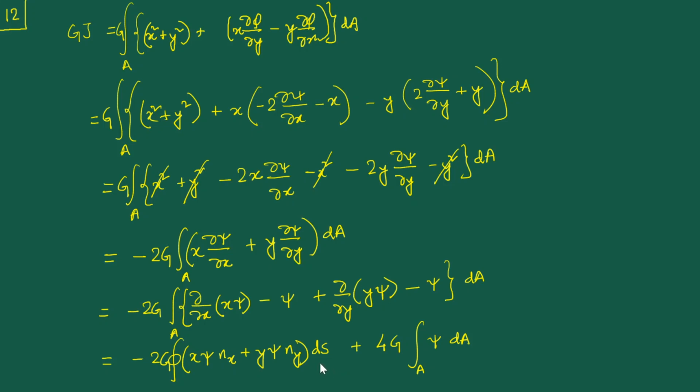All right, so basically what we have managed to do is to obtain the equations corresponding to the ones that we had obtained earlier involving the warping function, but this time involving the Prandtl stress function. And please note that unlike the approach that we had been following in the various chapters earlier, and even in this chapter, we did not really proceed by any variational route.